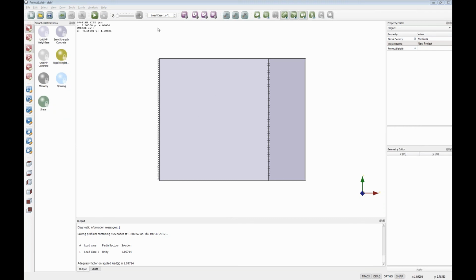And now the third question, can we apply line loading? So obviously I think up until now all you've seen is the ability to have pressure loading, and the answer to that is yes. You can see the purple icons up at the top of the software here are identifying the different types of loading you can have. So we can have point loading, line loading and pressure loading.